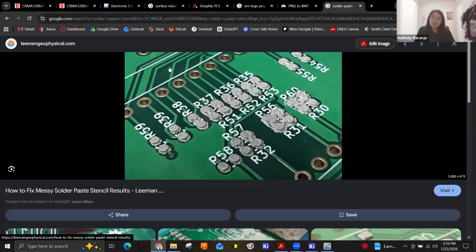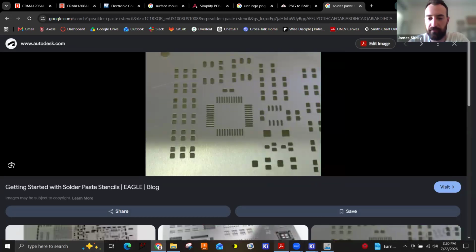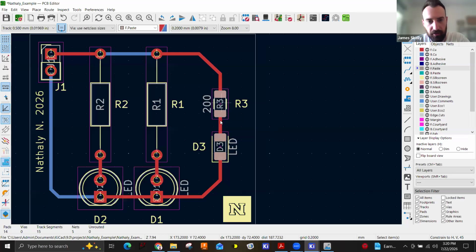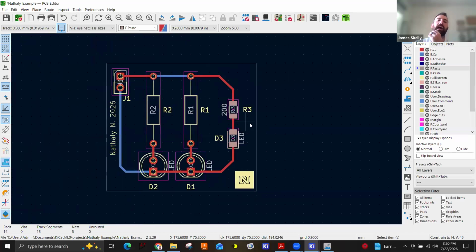Yeah, that makes sense. So when you're telling the fabrication people, I want this paste layer, like we have these gray squares, that lets them know if they're going to be making the stencil, they're going to cut these holes out in the stencil so that when you put your stencil down, that will actually be where the paste will go. So just to fill in the gaps of what some of these layers are that we're adding to the Gerber, so that it's not magic. You don't need to worry too much about this, but just so that you know.